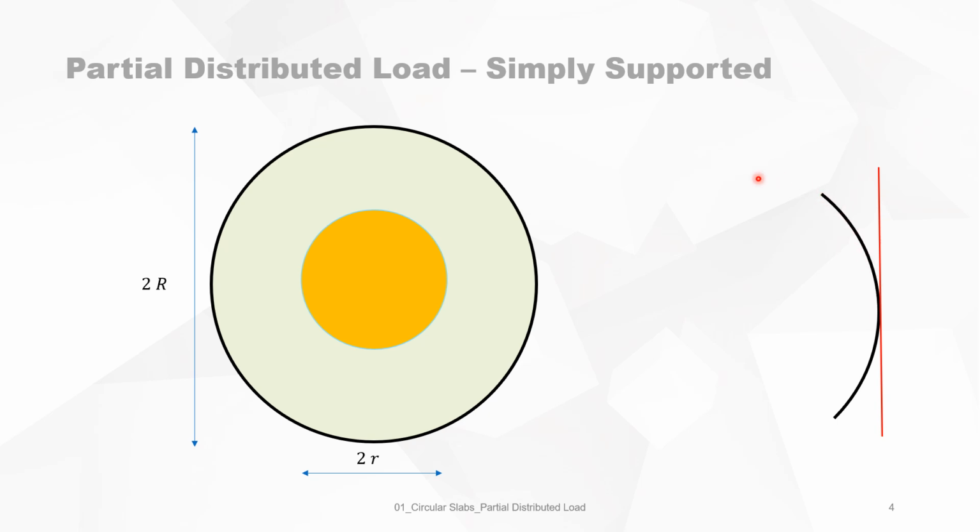So you have an infinite number of rotation axes. Let's take 3 of them to demonstrate. The yield lines are connected by this: when 2 rotation axes cross, then between those 2 crossings the yield line will be there.